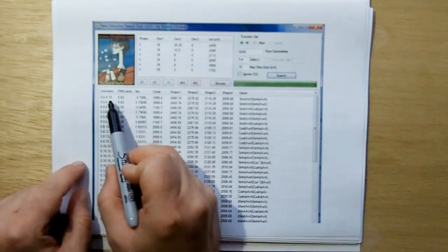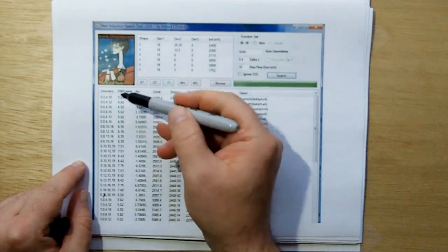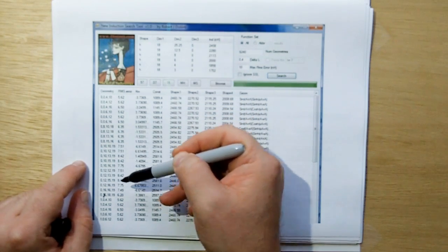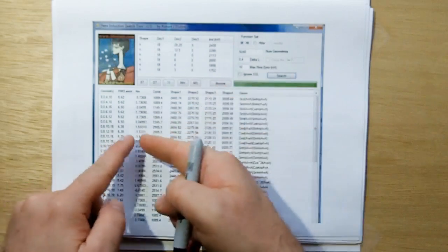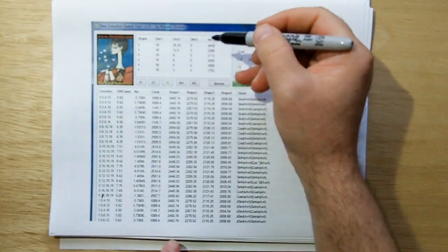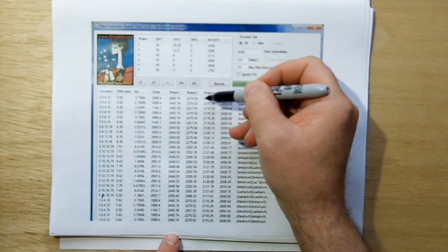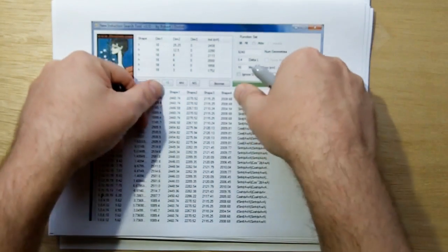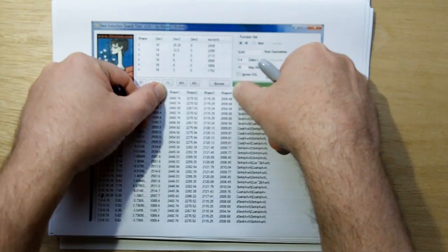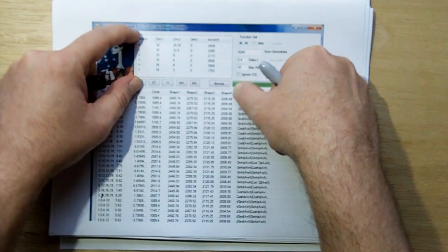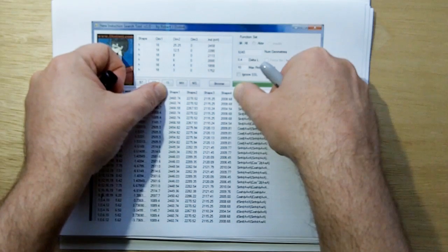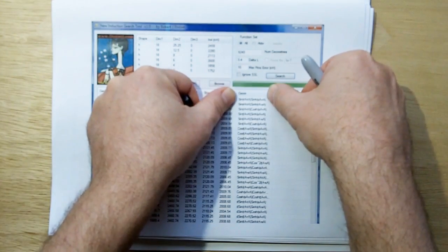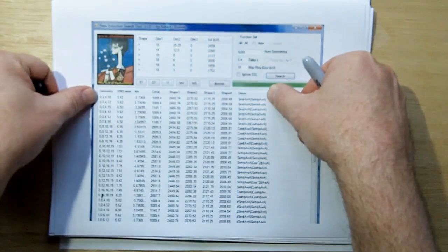And now what you have here is, this is the candidate geometry. This is the RMS error of the data. When it calculated, it went back and used the derived constants and computed the shape values. Okay, and then what it did, it is RMS of those. It only shows the first four shape values here. You can have any number of shape values in here that you want, but it's only going to show the first four computed inductances of the first four shapes. And this is just a simple text description of what this geometry over here means.